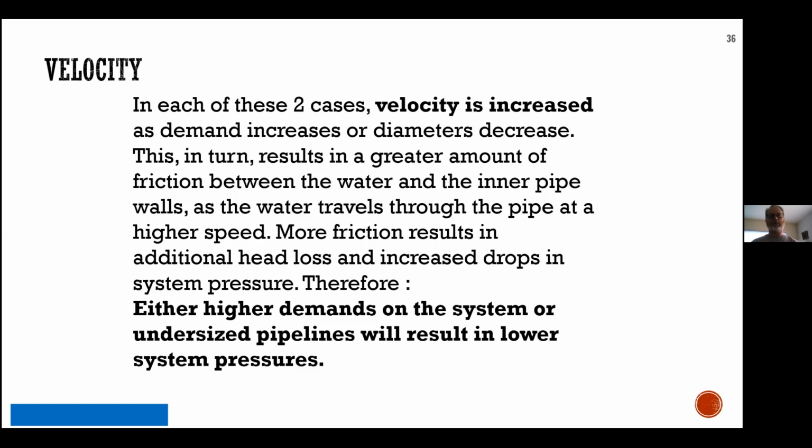So if the pipe is too small, or if we go, in this part of the world, from winter to summer, and everyone's now using water, in other words, a higher demand, we can have a lower pressure. And it's not unusual in this part of the world to have pressure at the outside tap or at the fire hydrant at the street of 60 psi, 70, 75 psi, and actually have that drop by like 5 psi in the summer. Doesn't sound like much, but over a whole system, it's noticeable.